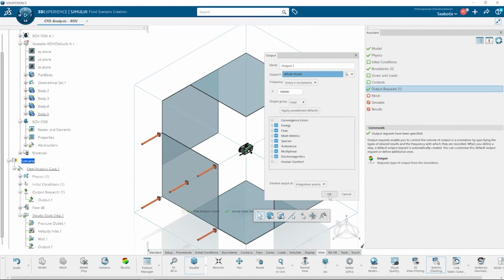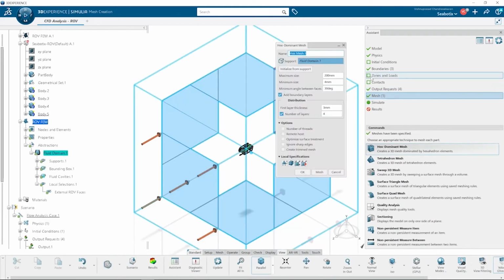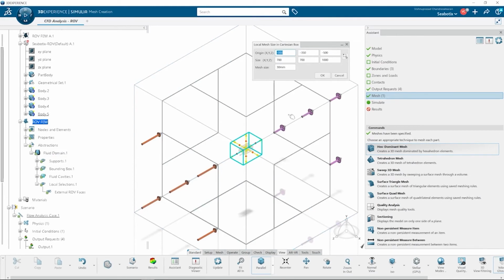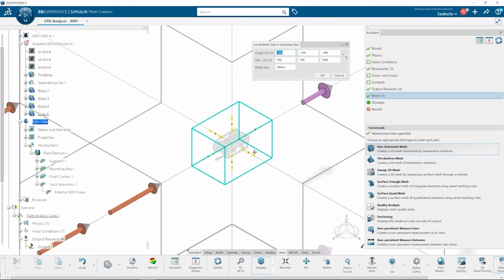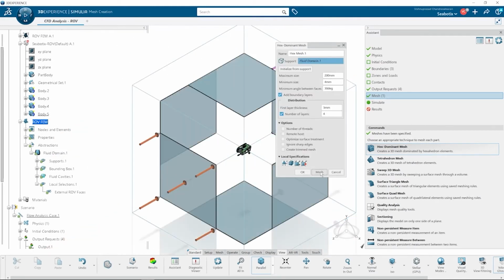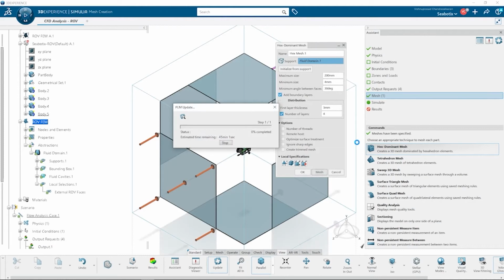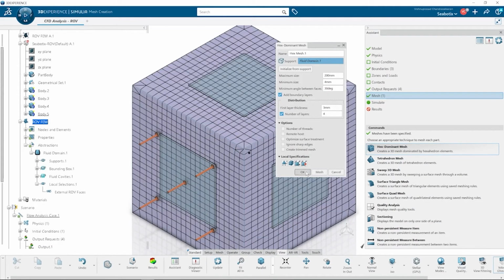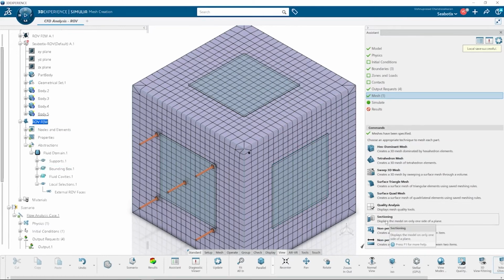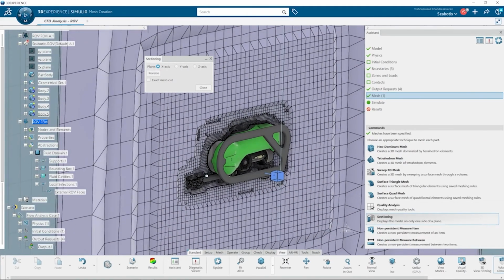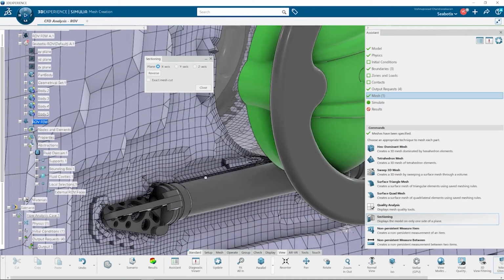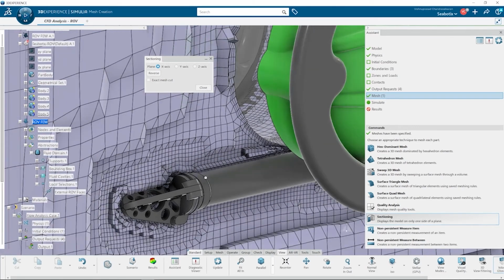With FMK's superior meshing tools, we can create a variety of body-fitted meshes and leverage advanced capabilities to even accelerate the process. The very desirable hex-dominant meshes are chosen for this study to reduce mesh element count while improving overall mesh quality. Meshes can be viewed interactively with the Sections tool, making it easy for visual inspection. Tools are readily available to estimate mesh quality to help with fine-tuning.